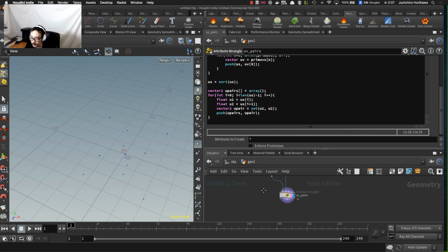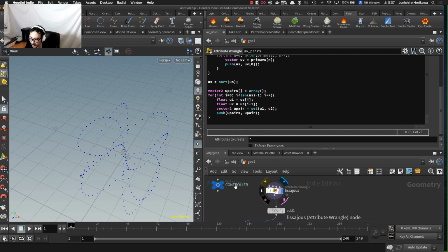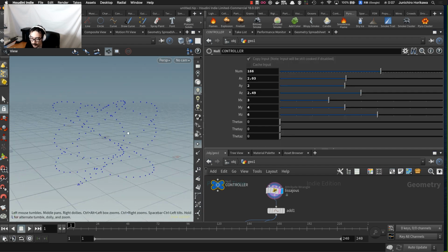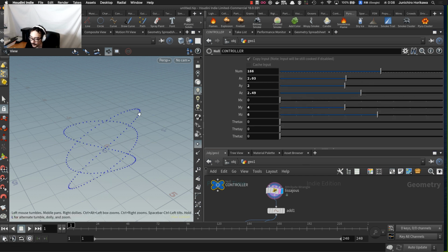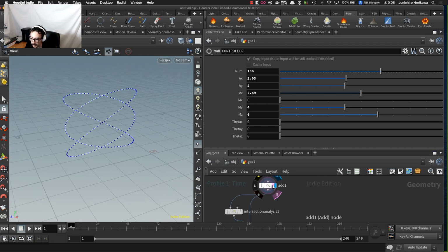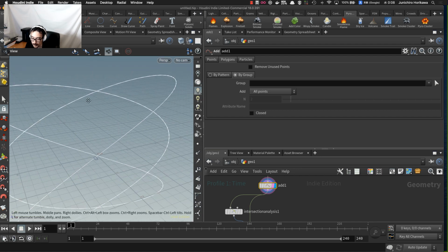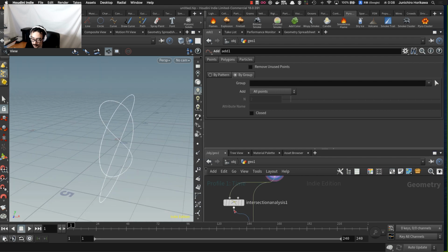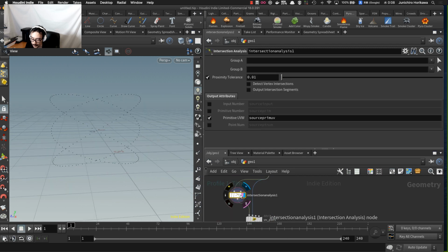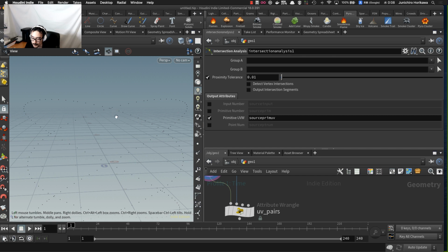That should work. Now sometimes if the curve is flat, the number of intersection points becomes vastly bigger than it should be. Like for example, if the m value is one like this, and you have a curve like this, you can see that there are duplicated curves like here, which creates a vast number of intersections. Now that is not what I want, because if you use all those intersection points as segmented points, then each curve length will be really short.